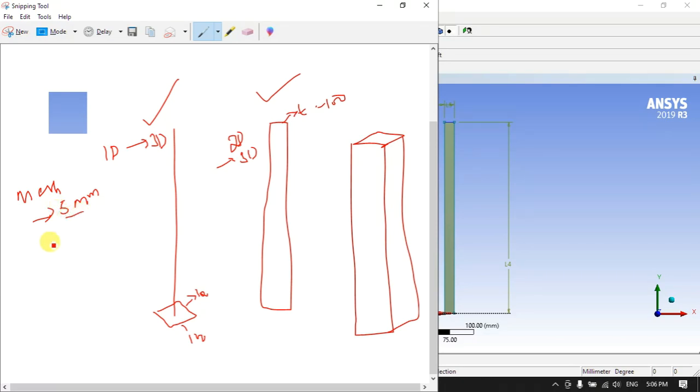Now, how many directions does this one have? Only one direction, which is given as 200. So can I divide 200 by the mesh division, 5? I can get a number of 40 meshes, so 40 is the number of elements for this one.